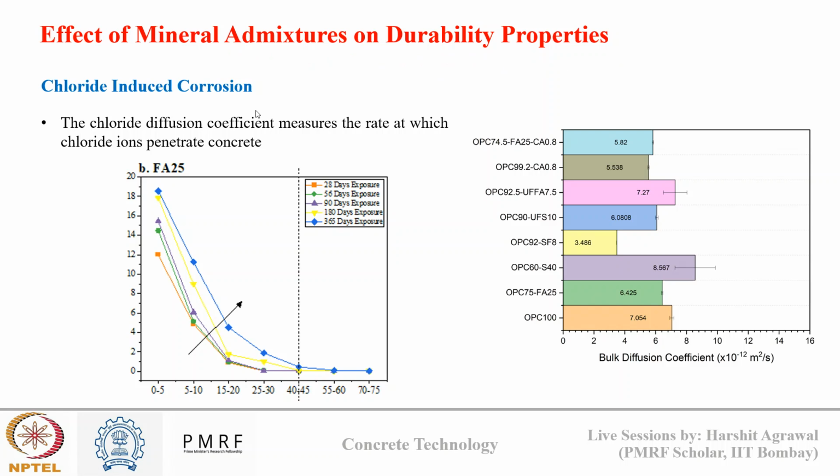So see, in field application, the concrete that we use is reinforced concrete. In reinforced concrete there is steel reinforcement that is embedded inside a concrete cover. The cover can be of thickness 25 mm, 50 mm, 75 mm based on the need. Why are we providing steel reinforcement inside concrete? Because concrete is weak in tension, so steel provides the tensile strength to concrete. Now this system of reinforced concrete was supposed to be inevitable, something which has a very high lifespan which won't collapse in any case.